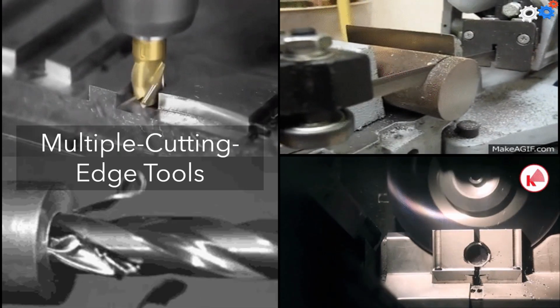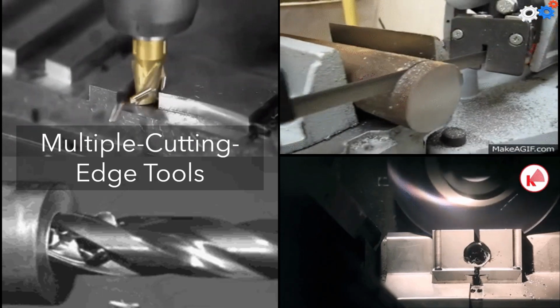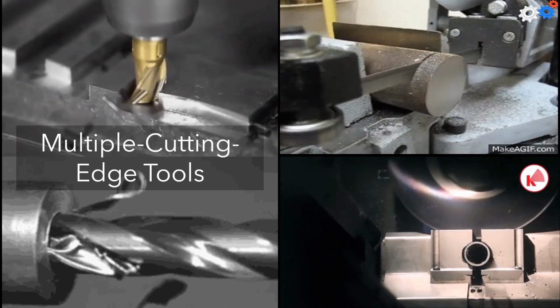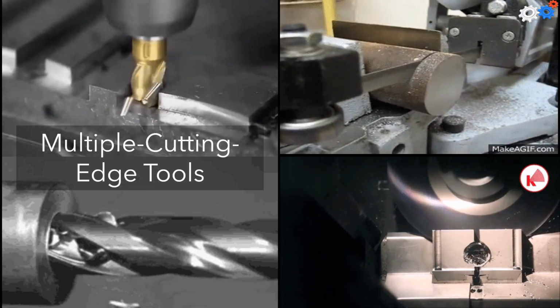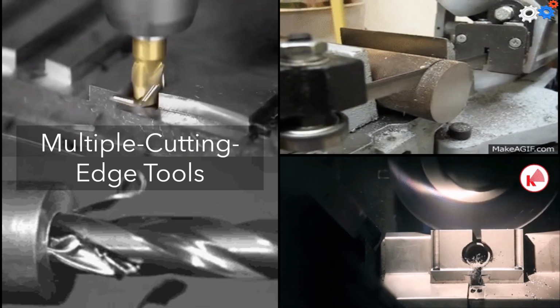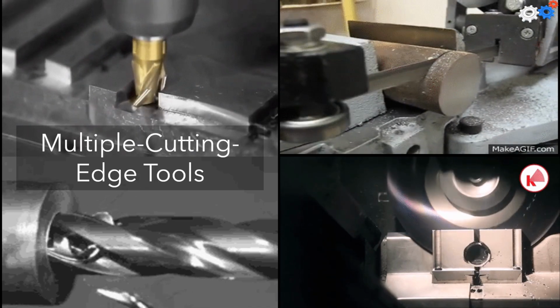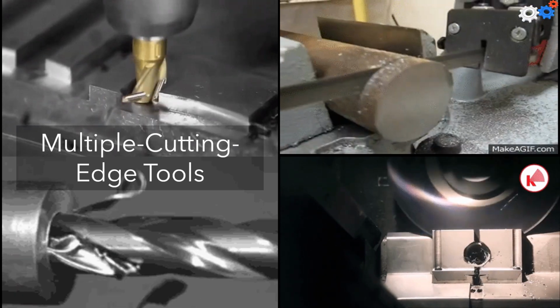Most multiple cutting edge tools are used in machining operations in which the tool is rotated. The primary examples are drilling and milling. On the other hand, broaching and some sawing operations like hack sawing and band sawing use multiple cutting edge tools that operate with a linear motion. Other sawing operations like circular sawing use rotating saw blades.